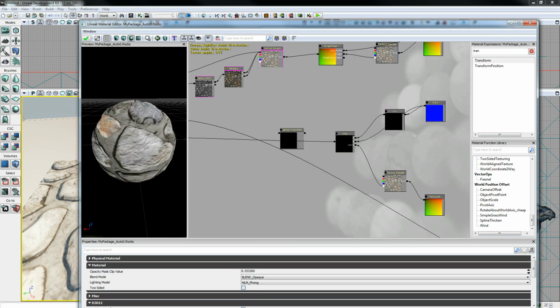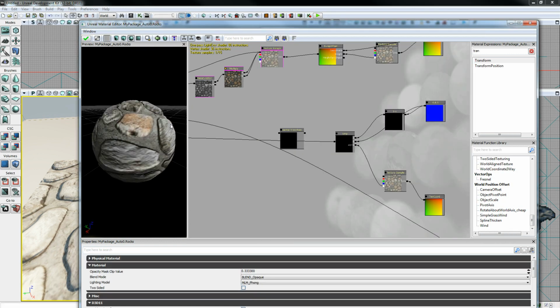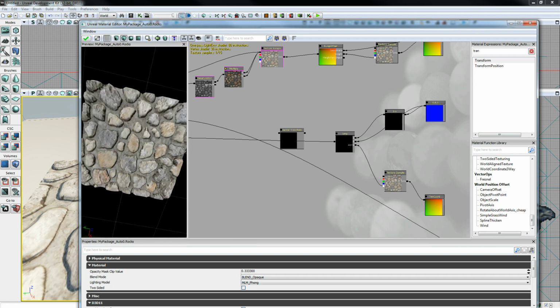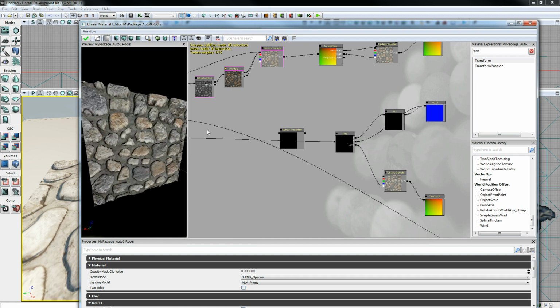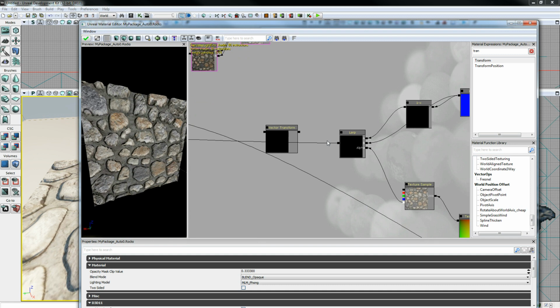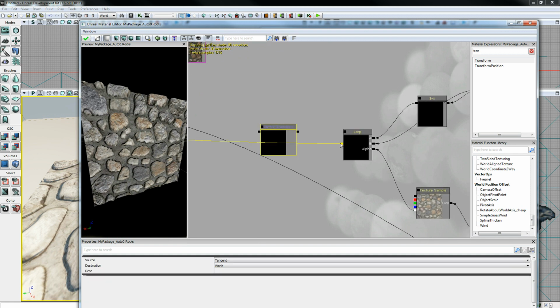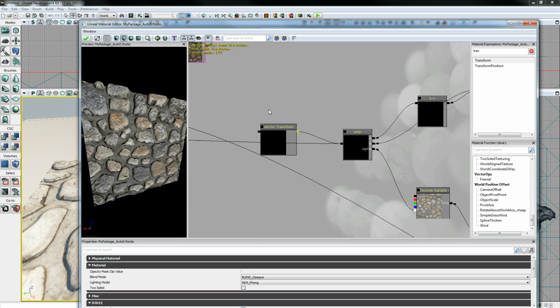you can see that everything is only going up. It's not pushing the bricks out. Like the top looks good, top's displaced, but everything else it's still flat, and the mesh is being displaced upwards. That's because it's not going based off the world, it's displacing based off the local. So you want to switch it so that it'll turn the tangent into a world.